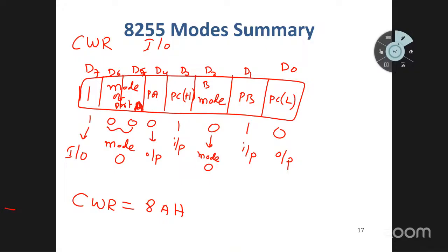This is how we can set this 8255 in this mode. To control the 8255 you can use this: MOV AL, 8AH. Next, what should we do?